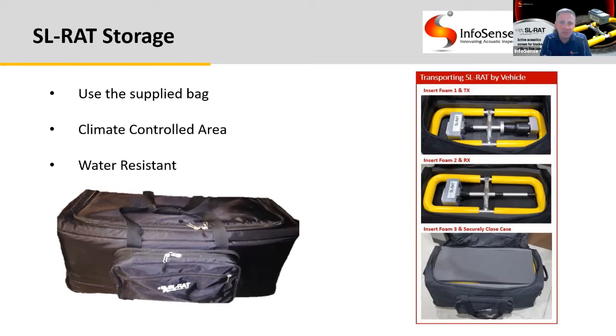The SL-RAT is designed to be water resistant, not waterproof. You can use it in wet weather, but it should not be submerged, and there are steps that can be taken to deal with water. Make sure the blue caps on the bottom of each control box are installed whenever not using the USB or charging ports. Don't push on the glass display when there is water present. And if the unit gets wet, it would be appropriate to towel dry it. Avoid heat sources or forced air around the speaker, microphone, or display.